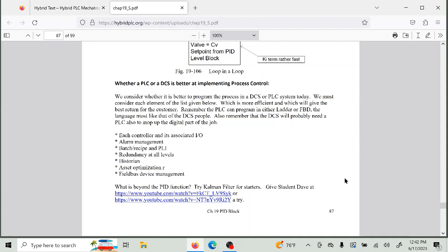You may have to work through these to find out if there's any reason why you would want to go to a DCS system. But if you want to have a taste for DCS, just flip over and write your program in FBD. Function block diagram in FBD looks very similar to DCS programming because they are the same. So if you look at FBD programming in the PLC, you basically accomplish the same programming style as done with DCS.